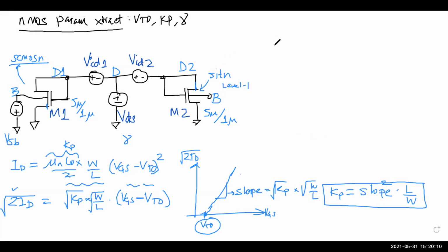Okay, so now that you have done problems and you're all experts, tell me quickly, someone, why does connecting the gate and drain assure that it is always in saturation? Yeah, go ahead, Praveen. Connecting the gate and drain makes sure that whenever it is on, obviously you have to first switch it on, then automatically it is in saturation.